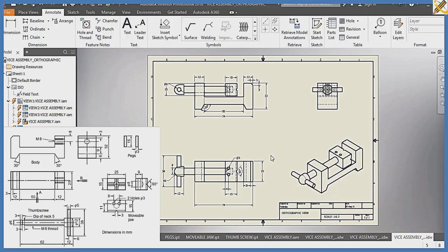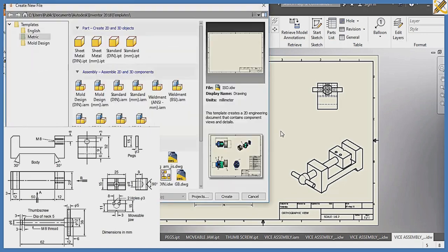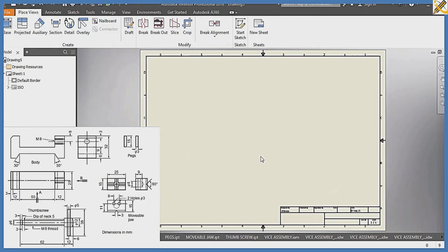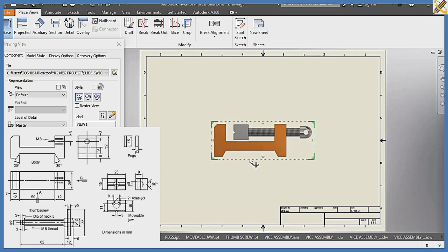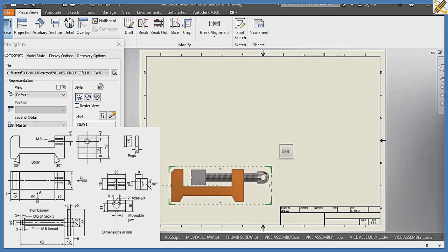So I've created the full assembly view: the assembly view, the assembly auxiliary view, the assembly part list, and the assembly orthographic view. So what next am I going to be creating? I'm going to be creating the assembly section view. Control N, create assembly section view. So base in this manner to pick the view. I think this view is better in this manner. Scale to 0.6, a little bit bigger, manageable, sitting right here.